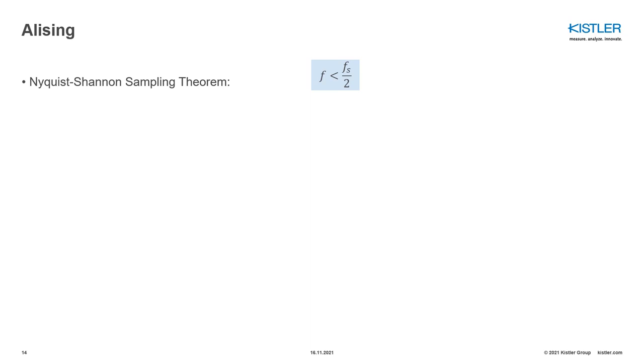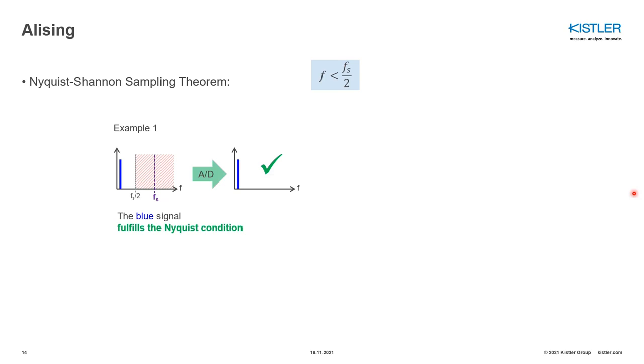So that's why we need to apply at least the Nyquist-Shannon sampling theorem, and it says that the sampling frequency has to be at least 2 times the maximum frequency that you want to measure. That's what Nyquist-Shannon says. Otherwise, you will have aliasing, so you will measure false frequencies, and I will explain this. So it means that if you have a true signal that you want to measure, your sampling rate should be at least 2 times bigger than that.